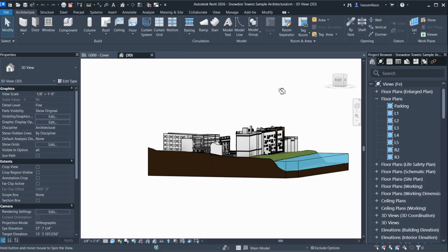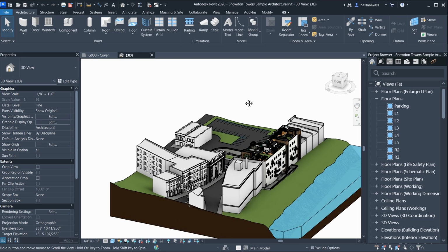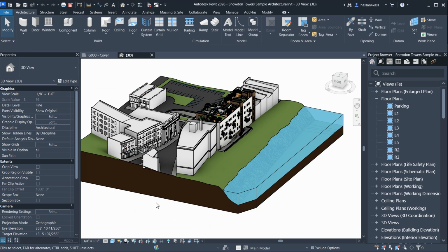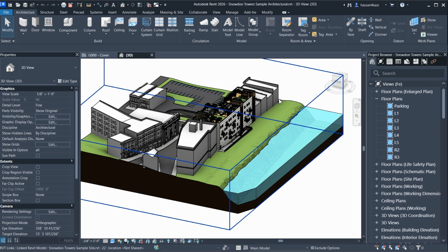We are in fact navigating in a big, complicated project. So be careful in 3D views. Make sure it's not placed on realistic. Choose shaded instead. So this one is called an orthographic or orthogonal view, which means all lines are parallel.